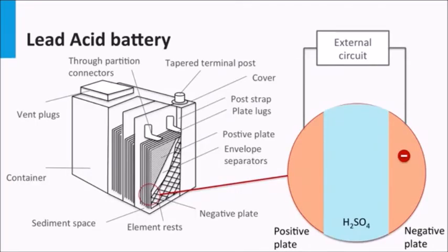Here, you see a typical construction of a lead-acid battery. As with most batteries, the lead-acid battery is composed of several individual cells, each of which have a nominal cell voltage of around 2 volts. Lead-acid batteries could have different types of assembly. When built as a block assembly, the individual cells share the housing and are interconnected internally. For instance, to get the popular lead-acid battery pack of 12 volts, 6 such cells have to be connected in series.